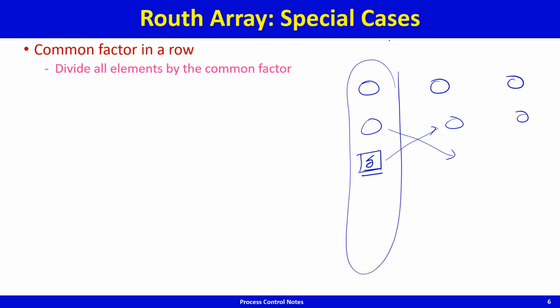That's the first way. The second way is, you got this polynomial p of s equal to 0. Now what you do is, you do the substitution s is equal to 1 by x, and once you do that, you will get the polynomial in terms of x, and now you apply the Routh array for p of x, and then that 0 won't occur in the first column. I usually apply this technique.